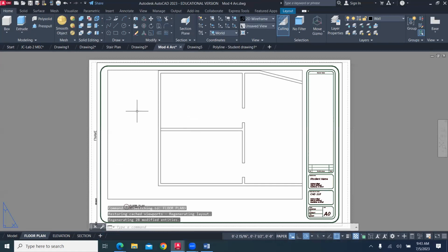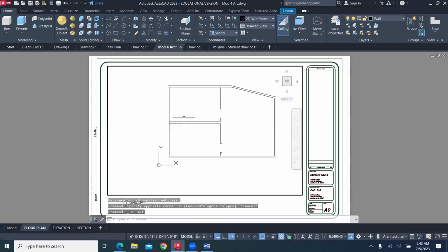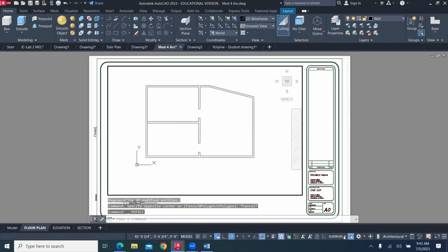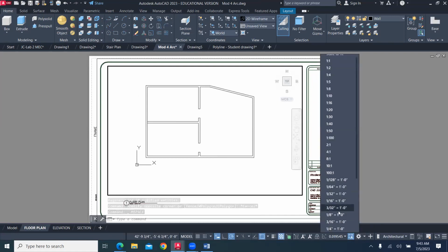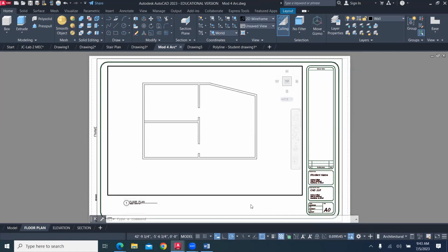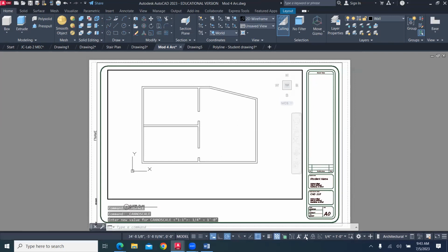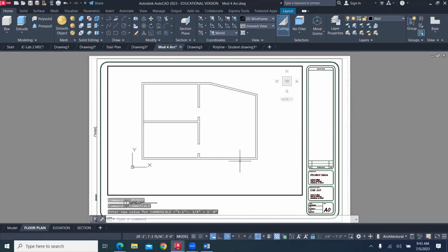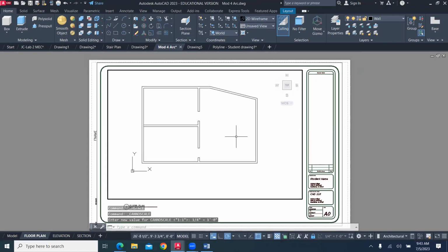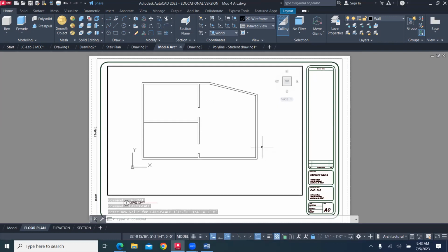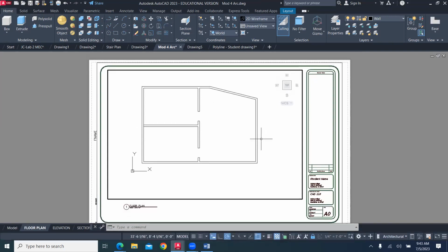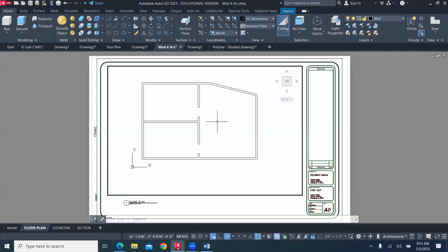put it onto our title block, double click in the viewport, and then we set the scale on the architectural drawings. And so if I say 1/4 of an inch equals a foot, and then I lock that in, then when we start to take these drawings down to, say, the facilities department or something, we can actually scale them and measure them, since the viewports are configured at scale when we print the drawings. And so that's your choice.